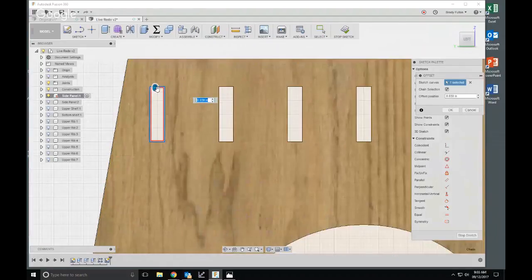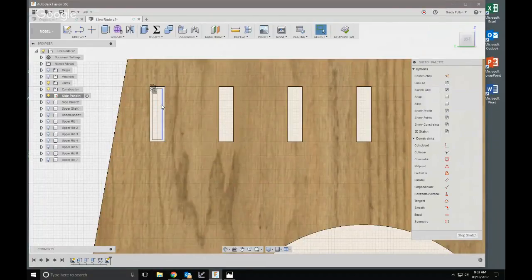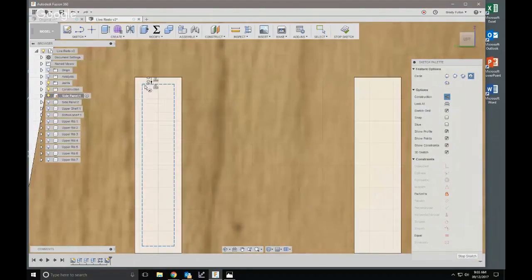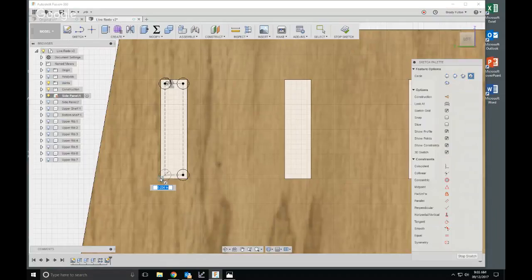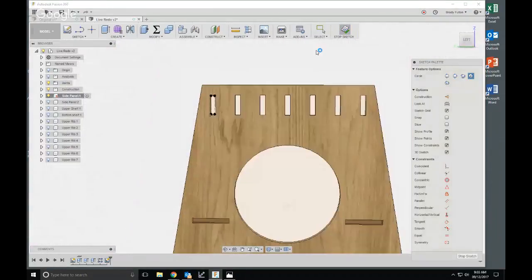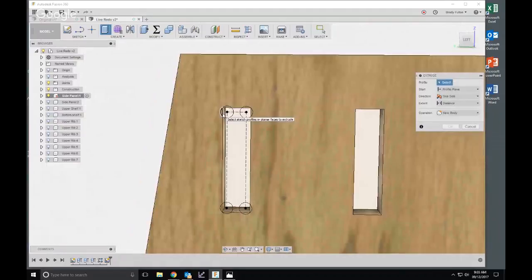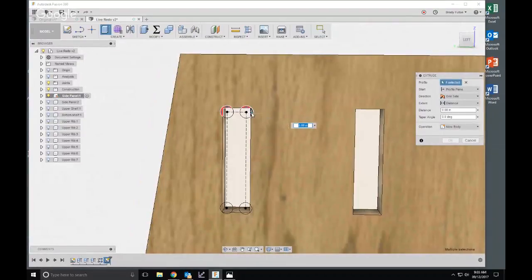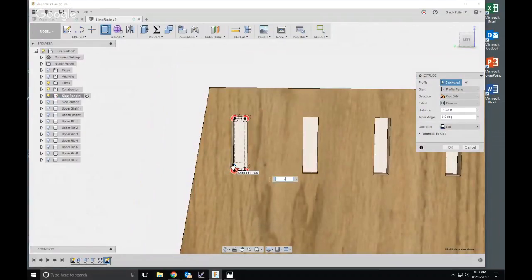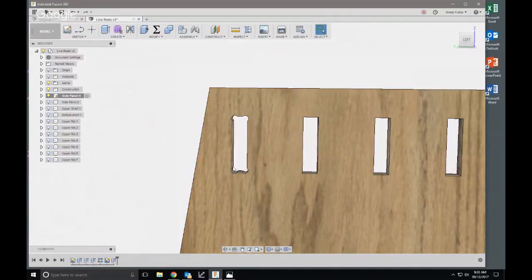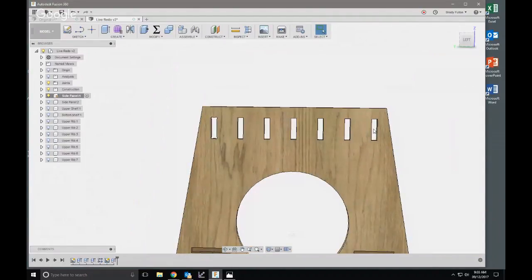An offset. I know that if I'm using a 1/4 inch cutter, I do 0.08 for my offset. Circle, center point circle, I do those. That's one way I create my dog bones. Stop sketch, extrude that. Nice, apply. Then I can iterate that across.